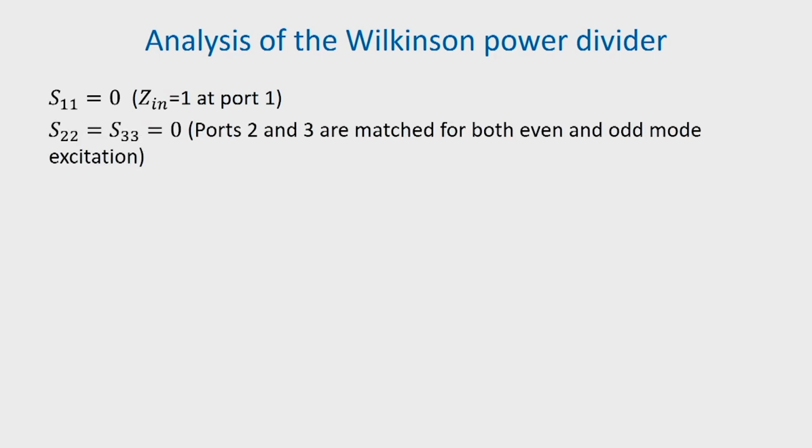We will have S22 and S33 equal to 0. This is because we have seen port 2 and port 3, they are matched for both even and odd mode excitation. So, S22 and S33 becomes equal to 0.